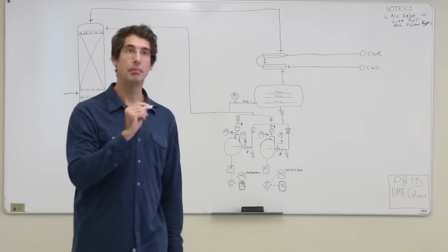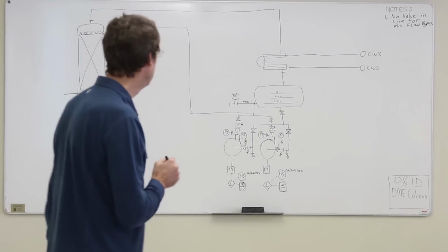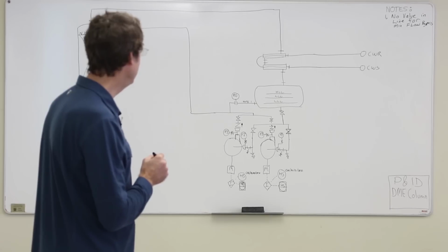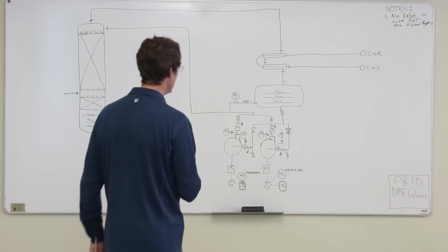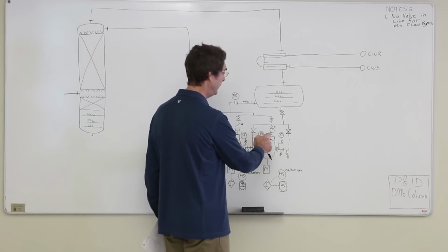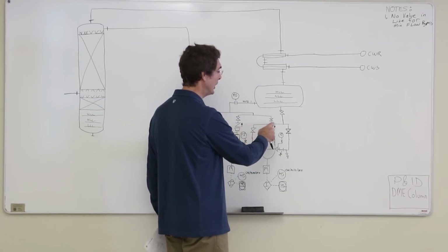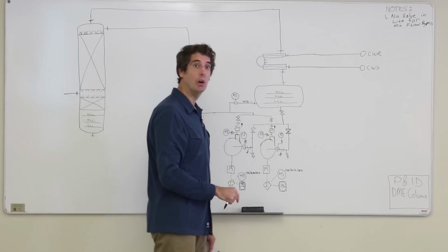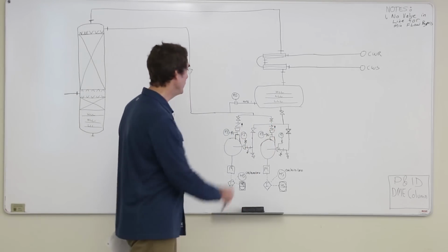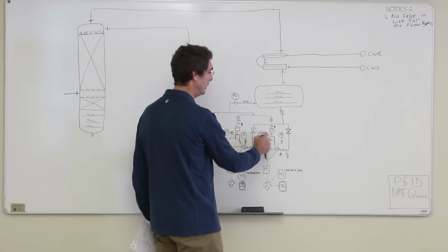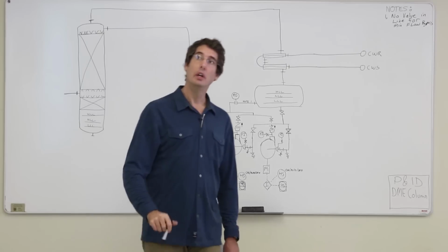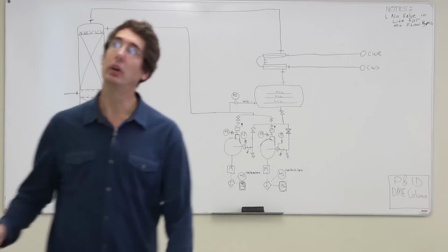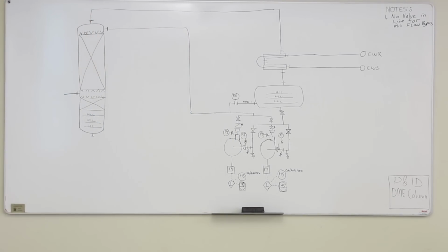Ted? What if you wanted to add a PSV or a pressure switch to the line? Sorry, pressure switch. It depends on where you want to put the pressure switch, but you probably want to put it on the discharge, and inside the block valve as well. So these are the block valves. Okay, so they're on-off valves. They're usually a gate valve, like that.